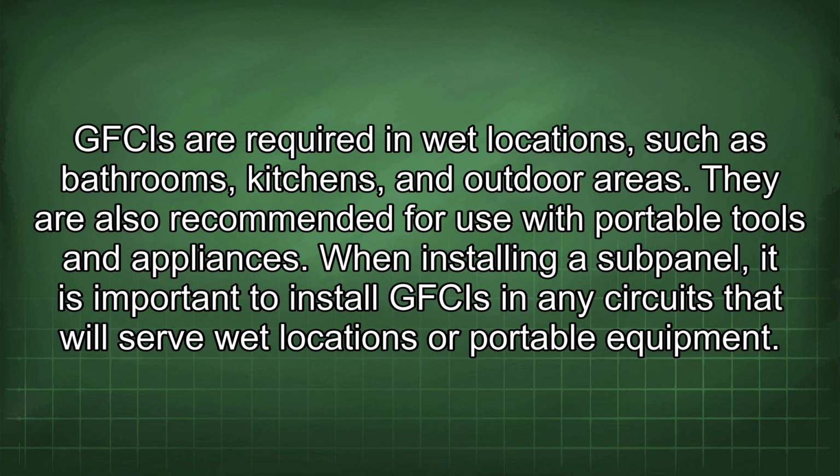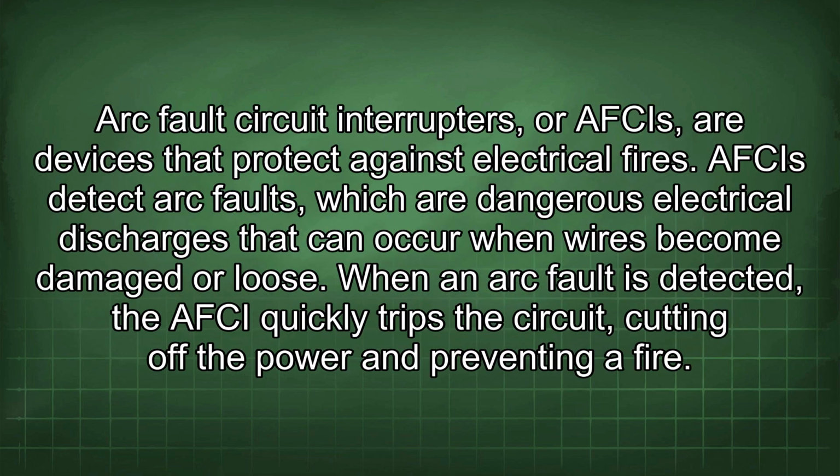When installing a subpanel, it is important to install GFCIs in any circuits that will serve wet locations or portable equipment. Arc fault circuit interrupters, or AFCIs, are devices that protect against electrical fires.